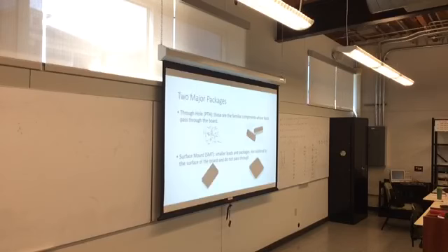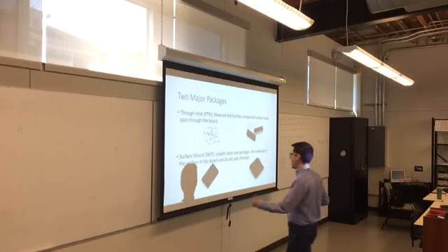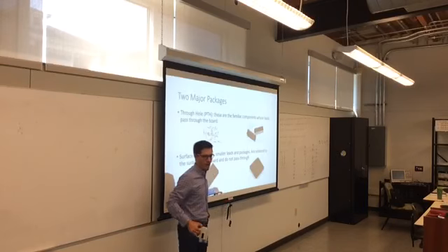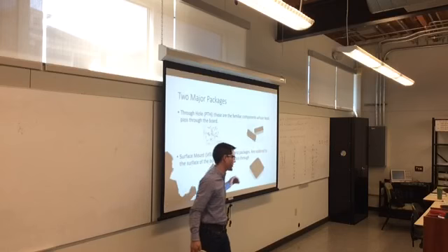It's honestly a lot easier to do than if she ordered that as a bunch of through-hole packages. The board would probably be about 3 times the size, and honestly, this is an accelerometer. You're not going to get it in a through-hole package. Some parts will not come in a through-hole package.